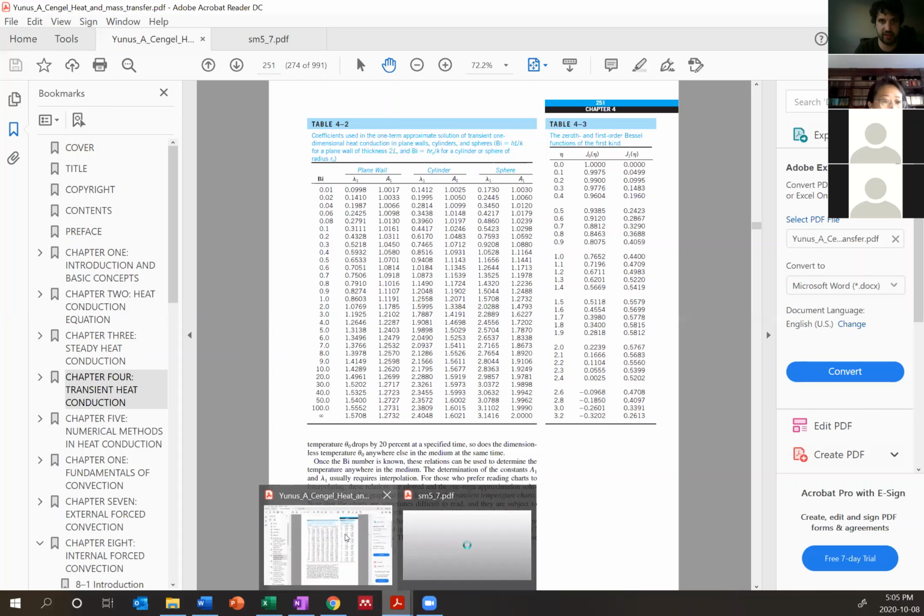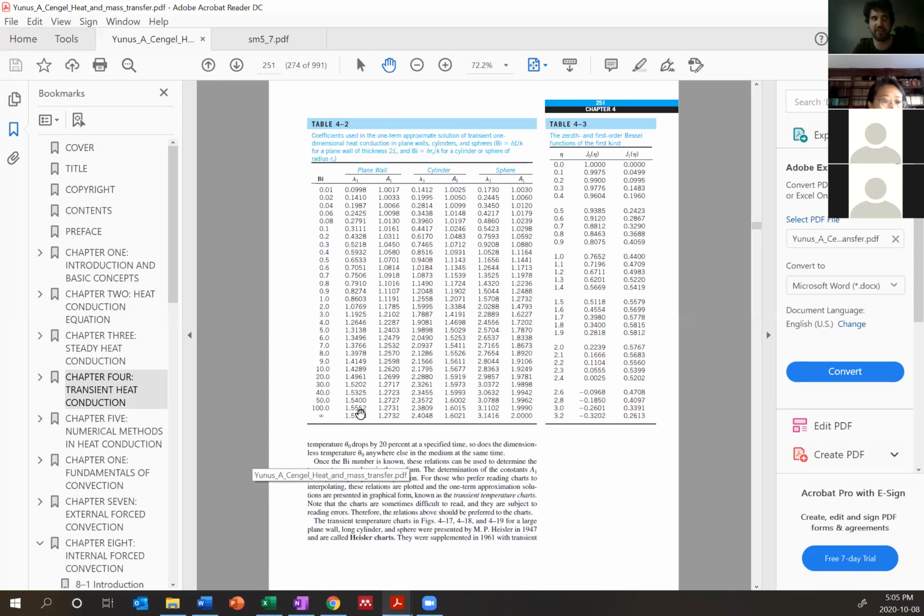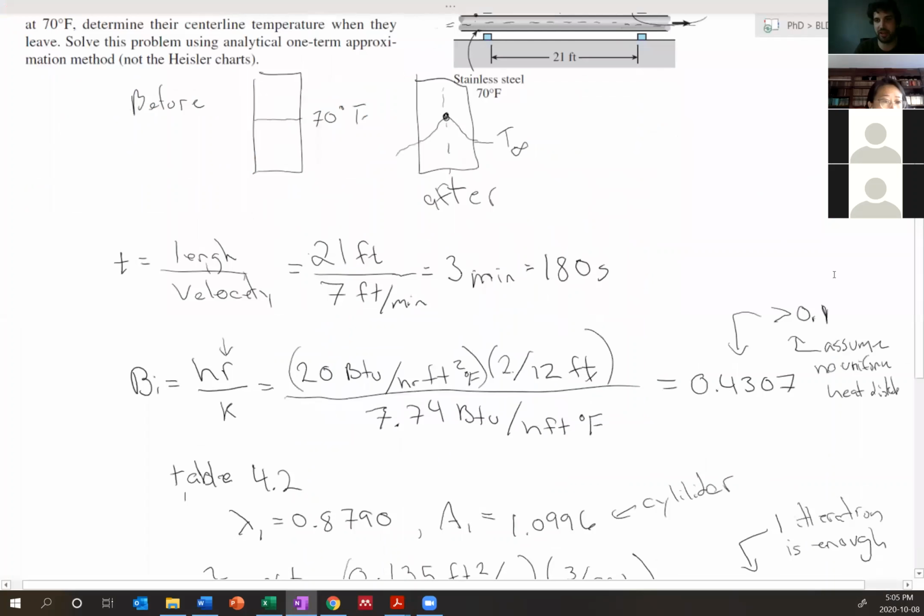Yes. Yeah. So, it's 5:05 now, so it's no issue giving away things for the quiz. The Biot number is the way we determine what kind of uniform temperature it is. It's basically a ratio of how much convective energy there is on the surfaces versus how much conduction there is. So if there's not a lot of convection compared to the conduction, so basically you're not removing heat that quickly, but heat is able to redistribute really quickly within the solid, then what we call that is a lumped heat capacitance model. We assume temperature is uniform through the whole thing, through the whole process.